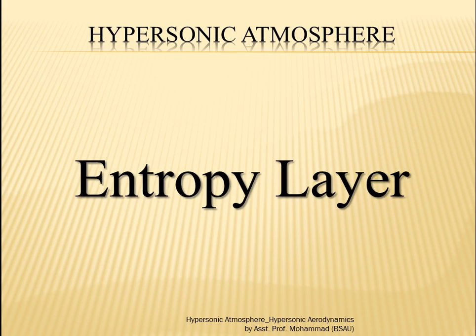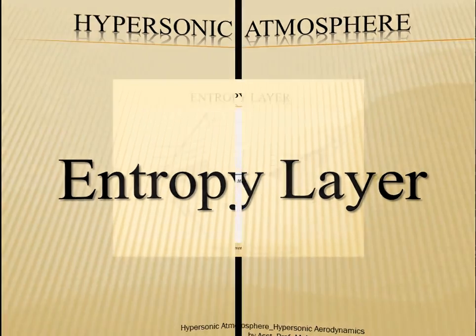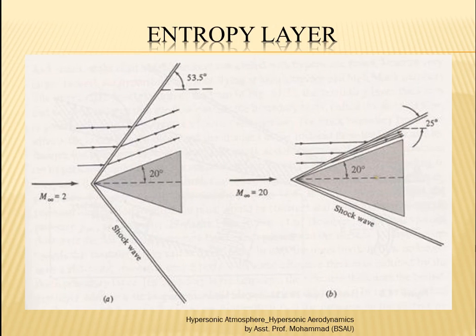Entropy layer. This is another characteristic of hypersonic flow which I am going to discuss now. Let us take the help of the earlier picture again. We know that when a conical leading edge flows in a supersonic flow regime, the shock remains attached to the body, and the strength of the shock remains almost the same throughout the length.